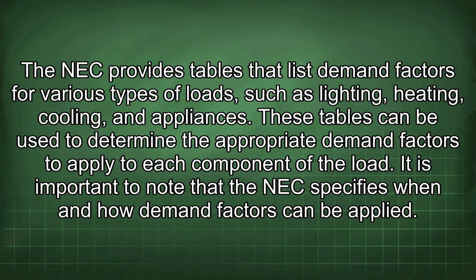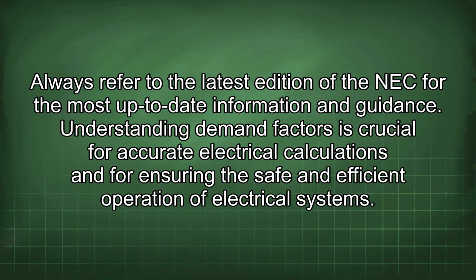The NEC provides tables that list demand factors for various types of loads, such as lighting, heating, cooling, and appliances. These tables can be used to determine the appropriate demand factors to apply to each component of the load. It is important to note that the NEC specifies when and how demand factors can be applied. Always refer to the latest edition of the NEC for the most up-to-date information and guidance.